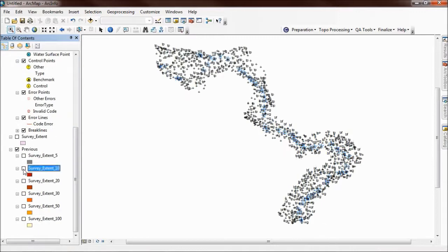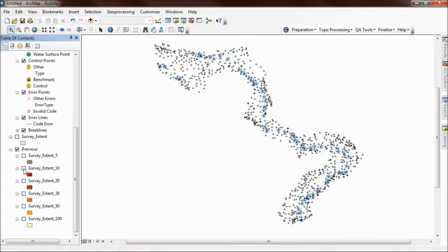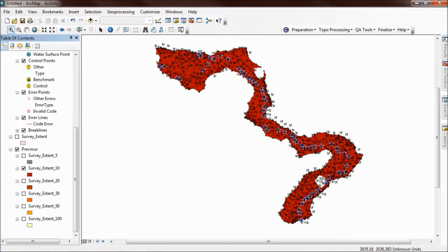So really the solution is somewhere between this 10 or 20 meter solution. And you have two choices here. You can either edit the polygon down from 20, which is probably the easiest thing to do. Just come in here and move these vertices into the bend, or you could just as easily go into an edit session on this polygon, delete this donut, and maybe join across this little concavity in the data here.